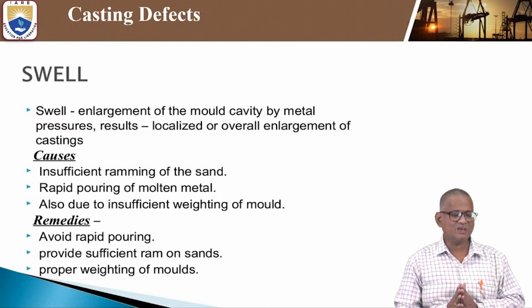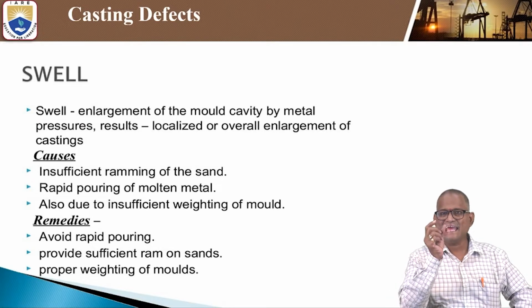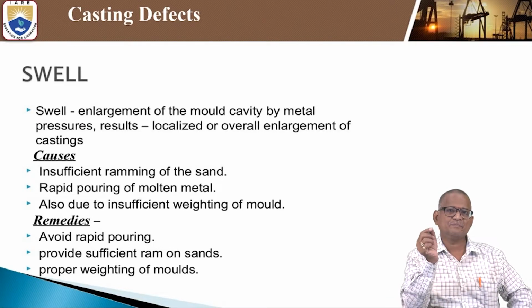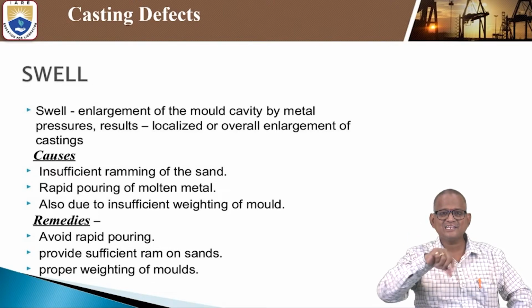So let us see swell. Swell is an enlargement of the mold cavity by metal pressure, which results in localized or overall enlargement of the casting.